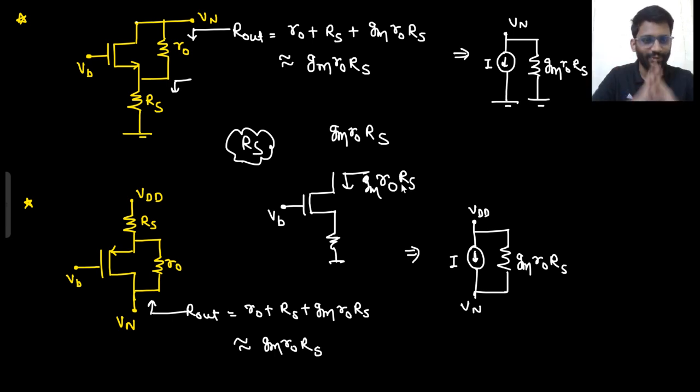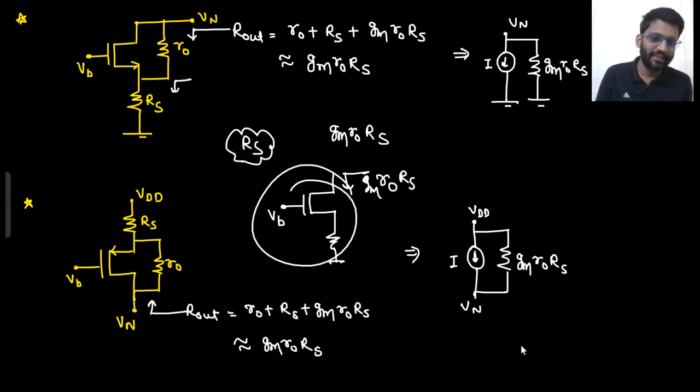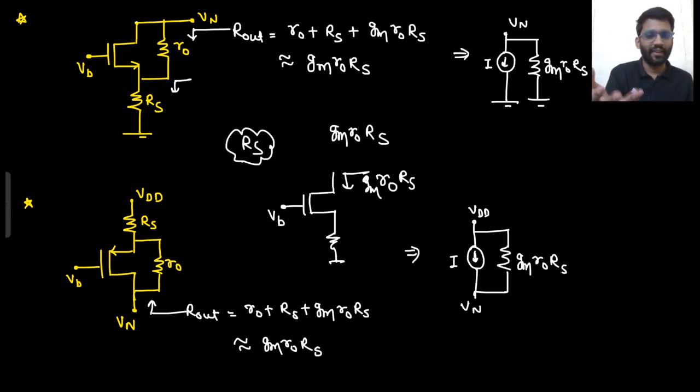If I use another of this circuitry in place of Rs, my impedance will be higher. But we don't want to use it like that. If I keep on adding, my impedance will be very high, but we don't want that much circuitry. Minimum circuitry we need to use. If we use that many elements, power consumption will be more, and the device will be costly. The chip will be costly. But you don't want to design a costly chip.